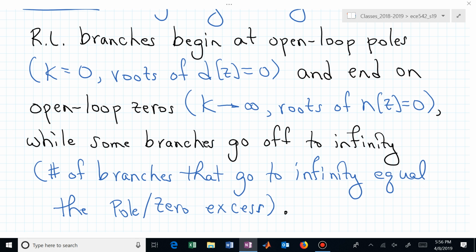It's going down the negative real axis, isn't it? That's where we're going off to infinity. As we crank up the gain k, one of those closed loop poles is going to zip off to minus infinity. That's unstable. So we probably can't crank up the gain at will. We've also talked about a pole zero excess of 2. When we just had 2 real poles, then our branches going off to infinity are now at plus 90 and minus 90 in the complex z-plane.